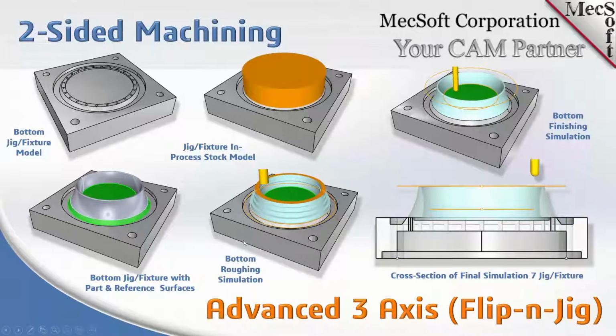And basically that's just going to guide the tool past that edge to maintain that feature in the actual part after it's machined. So in the second or center column, you'll see in the top, you'll see the in-process stock. It's already been cut on the bottom side. It's been flipped over, and it's been set on the jig or fixture.